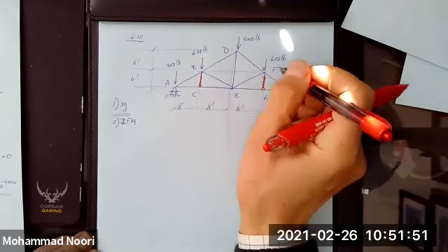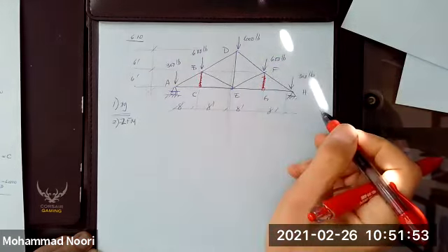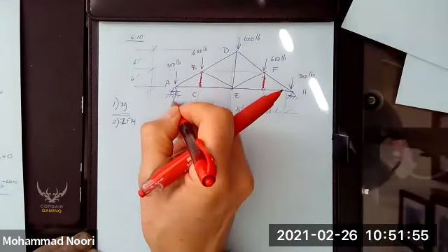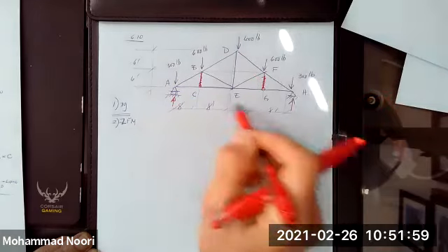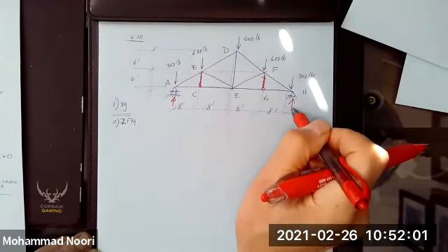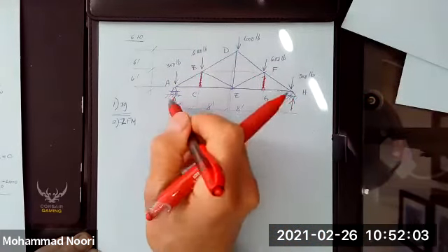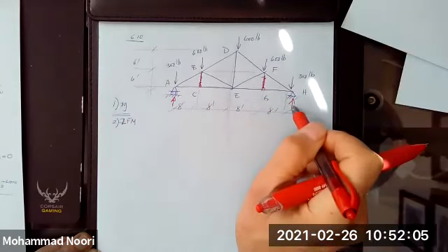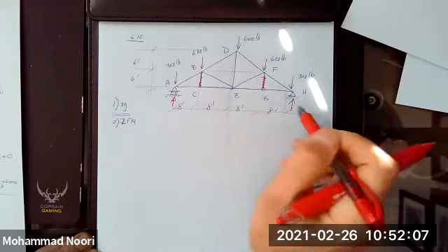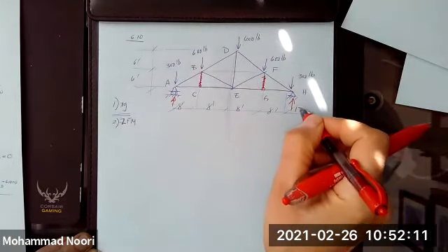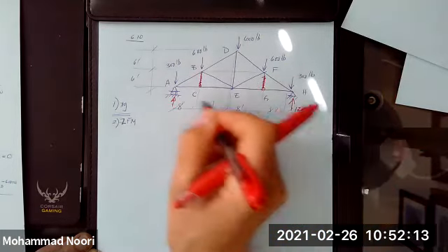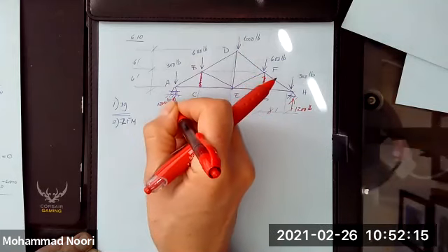One, without any calculations, you do know that half of the load that is on the truss goes here, the other half goes here. So you can quickly write the value for these reaction support forces. This is 2,400. So this is 1,200 pounds, and this support carries 1,200 pounds.